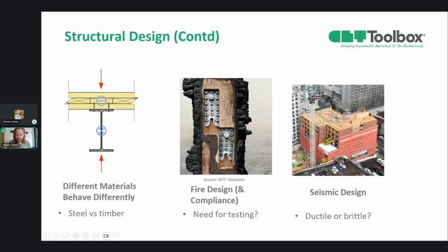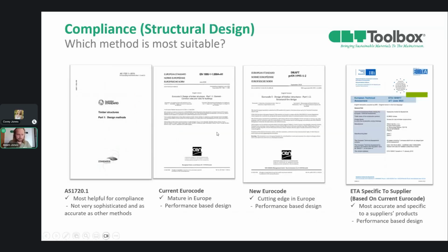Another factor in terms of structural design, you've also got seismic design. So thinking about the timber element, it's brittle. The fixing element is ductile typically. So designing for seismic, you want to be on the ductile design and how the timber interacts with the steel.